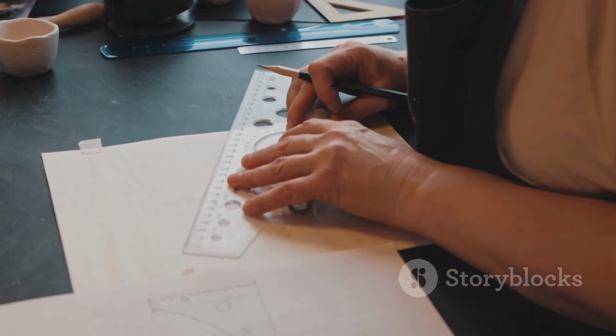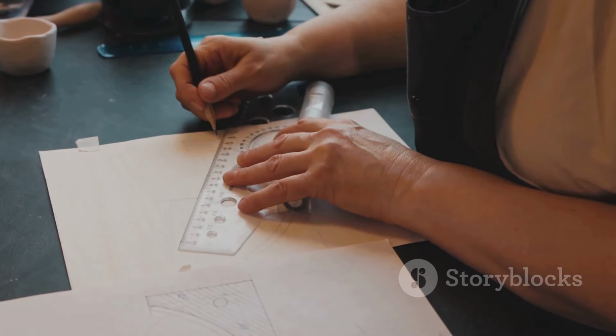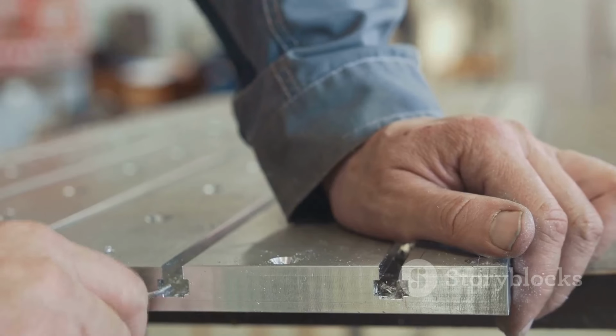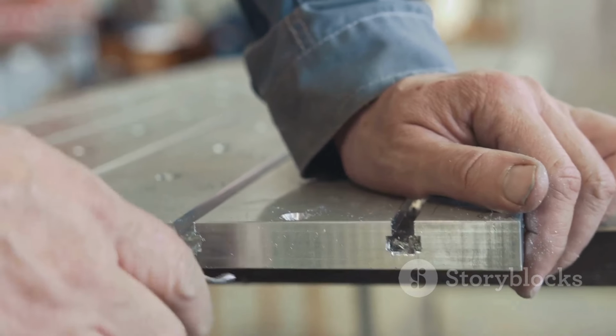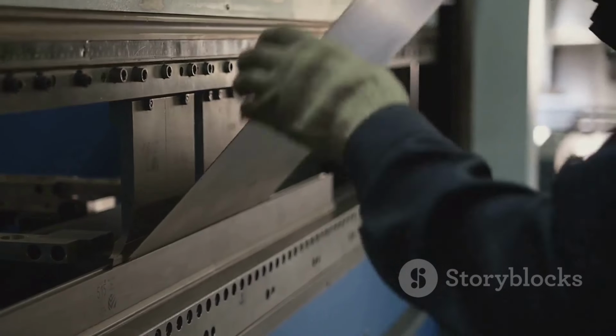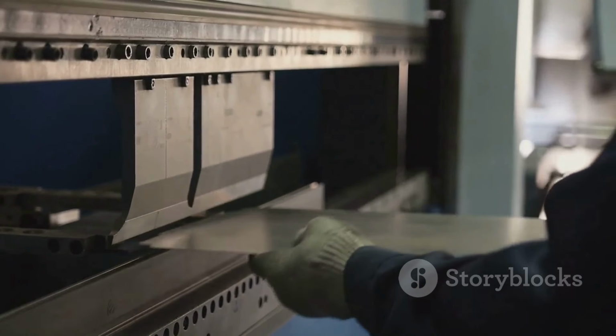Sketch a rectangle with the desired dimensions for your box's bottom. Use the Edge Flange tool to create walls for your box. Select each edge of the base flange and specify the desired height for your box walls. Add flanges to the top edges of the walls using the Edge Flange tool again.